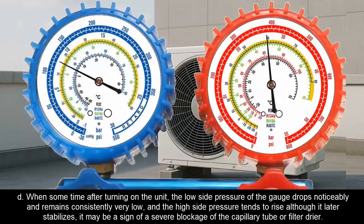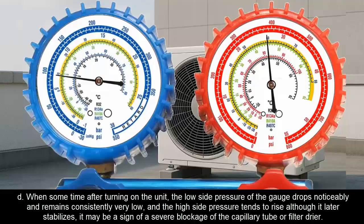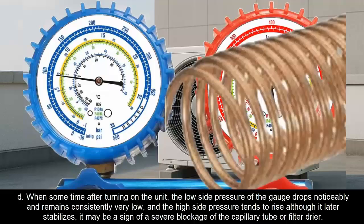D. When some time after turning on the unit, the low side pressure of the gauge drops noticeably and remains consistently very low, and the high side pressure tends to rise although it later stabilizes, it may be a sign of a severe blockage of the capillary tube or filter dryer.